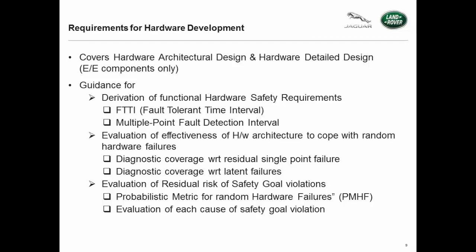So diagnostic coverage is calculated for single point failures, residual single point failures, and latent faults. And also the probabilistic metric for random hardware failure, PMHF, that evaluates the residual risk of safety goal violations. Although there's actually two methods for that, or you can evaluate it by looking at each case. It's a cut set analysis, and failure rate classes like FMEA are assigned and have to meet certain targets.